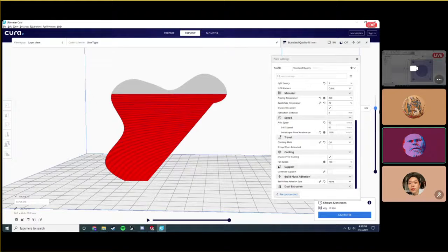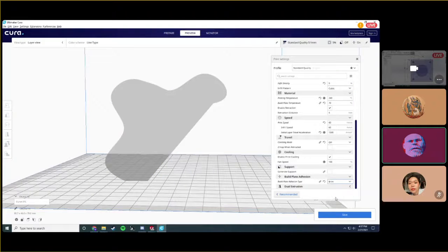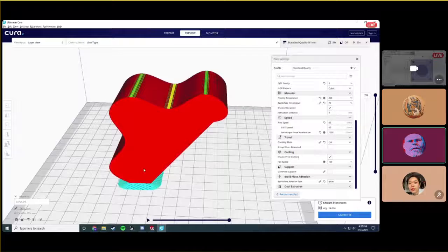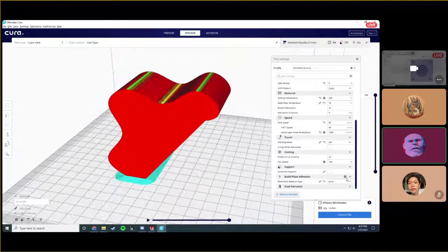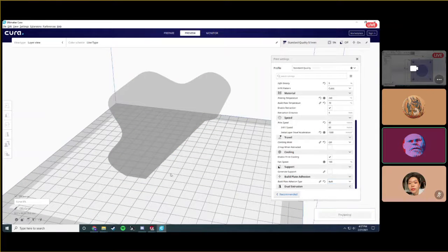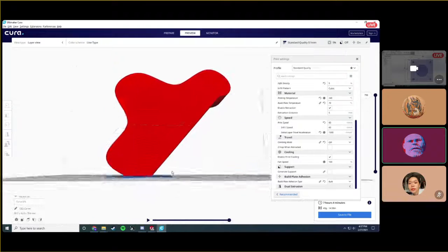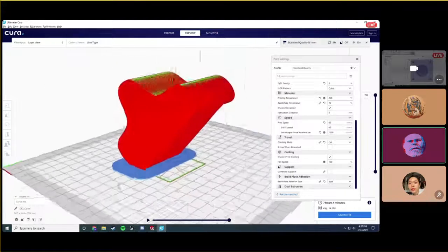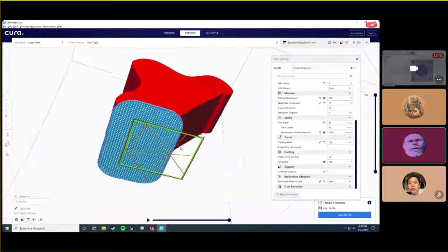Over the course of printing this model, with the bed moving back and forth, it is likely to fall over or be knocked over or just come undone, and then your print is ruined. That will probably happen towards the end of your print, so it would be a lot of time and material wasted. So you can add build plate adhesion, like a brim, which basically gives you more surface area attached to the bottom. You can also add a raft, and that support material can peel off after you take the part off the build plate. A raft is like a whole other thing. It elevates your print and prints on top of it.